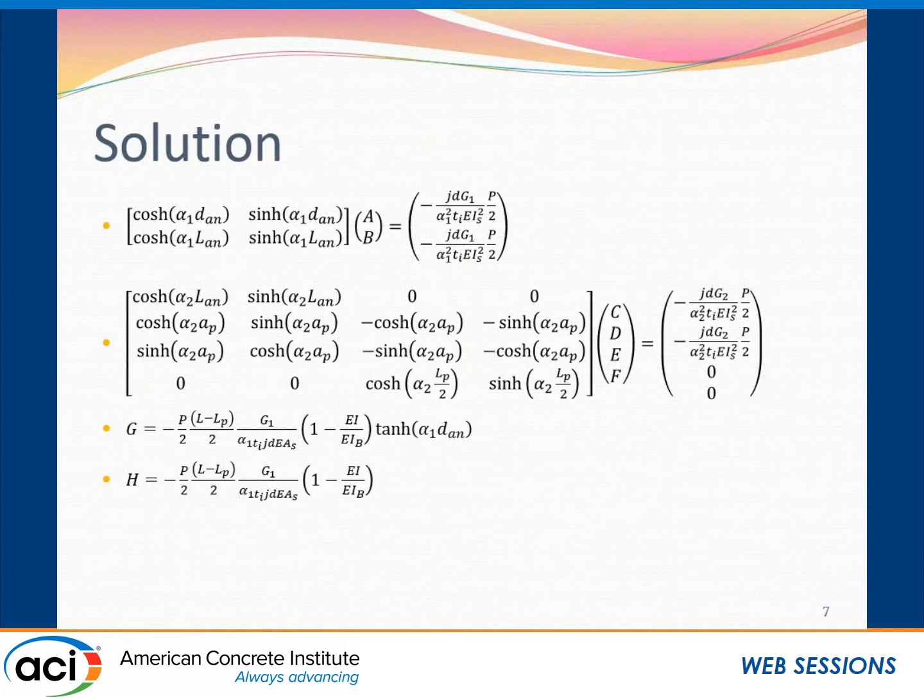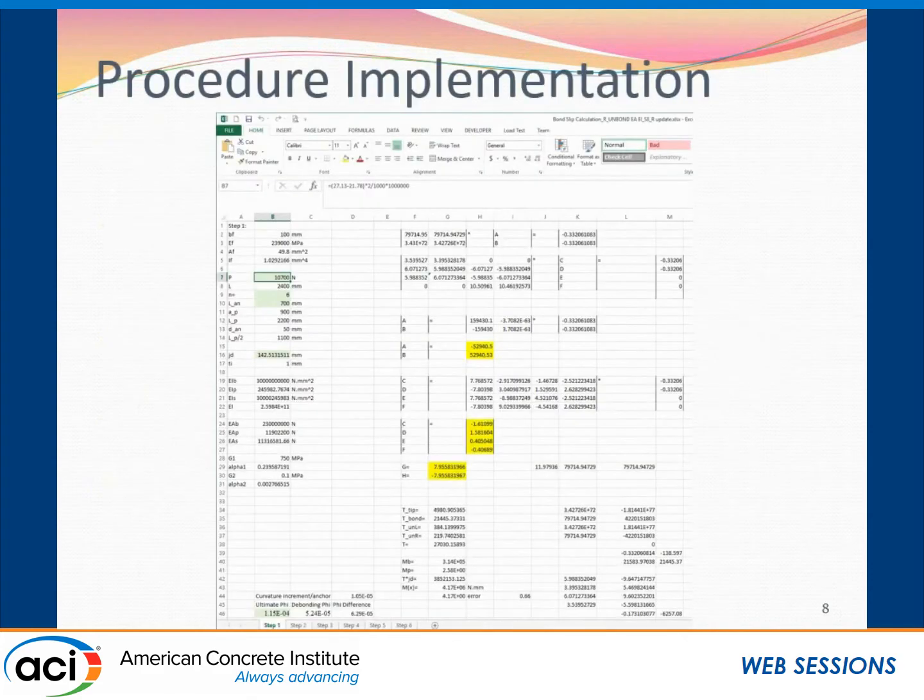Several of these matrices and equations, and if we apply them, we're able to calculate the constants and then use them in our model. So now that we have our model, we moved ahead to implement it. We implemented it in a spreadsheet where the inputs are the geometric and material parameters of the test specimen to be investigated. And here we have our matrices. We invert the matrices in order to solve for the constants. The analysis is done by applying the load incrementally beyond debonding.